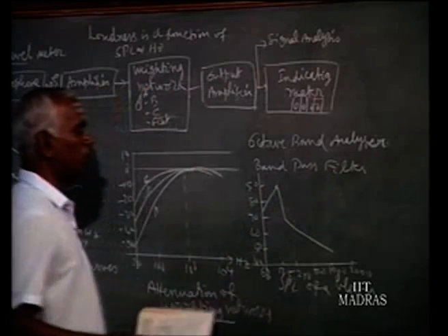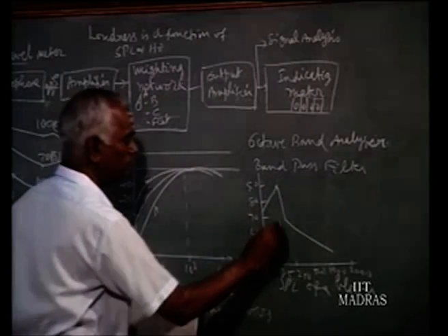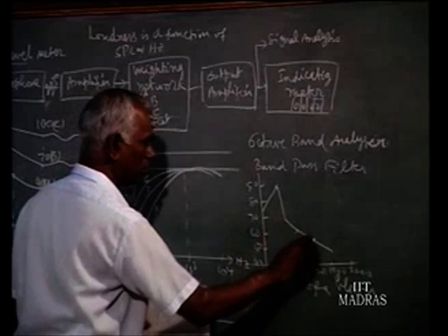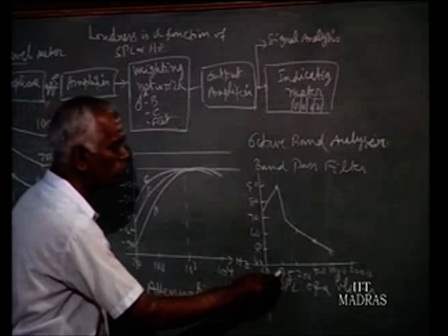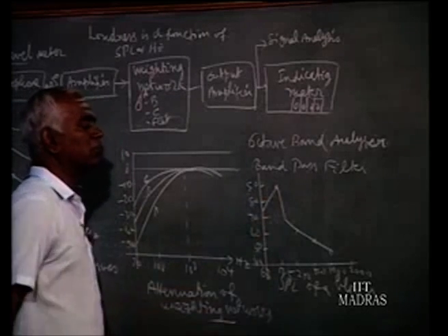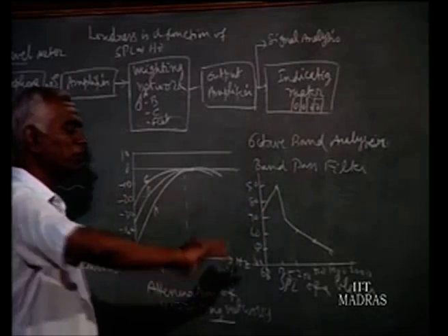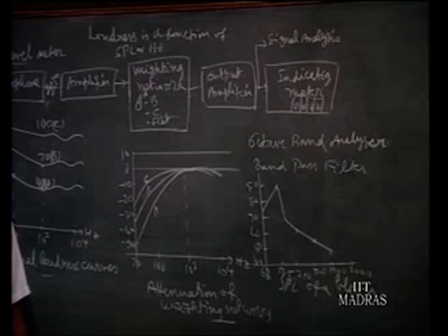So, this is the plot of the different center frequency. We got this plot. From here we know that at 125 hertz it produces the maximum noise. Probably 125 hertz may be the rotating speed of a gear machine.